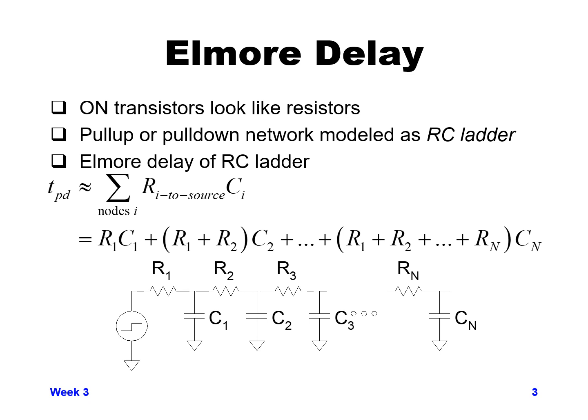When you take the propagation delay through that RC ladder, you can see that it's not just a function of R1 C1 multiplied by some constant K, for example. If you had three in series with each other, you wouldn't just take R1 C1 times 3, because once you get to the second device, you now have R1 plus R2 in series with each other times C2, and when you get to the third device, it would be R1 plus R2 plus R3 times C3.